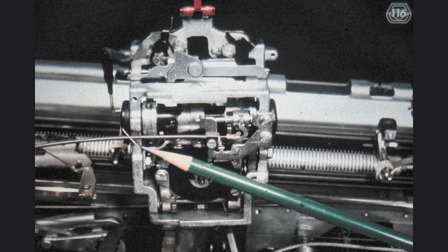The velocity control cable should be clamped into place in such a way that it only lightly touches the inner surface of the power frame when the carrier is at the extreme left position. This, of course, can only be checked when the carrier is back in the machine.